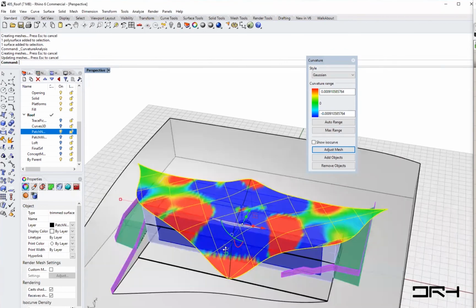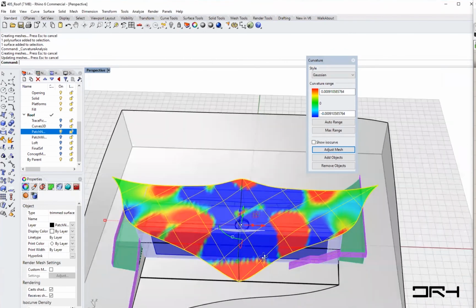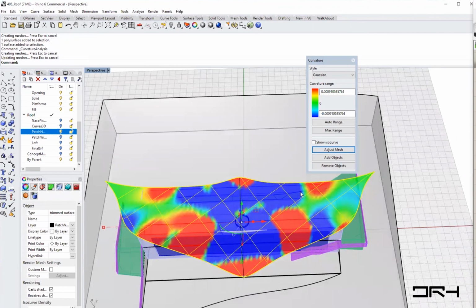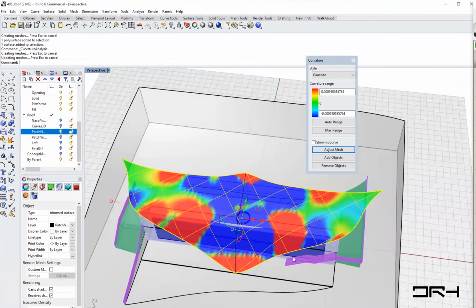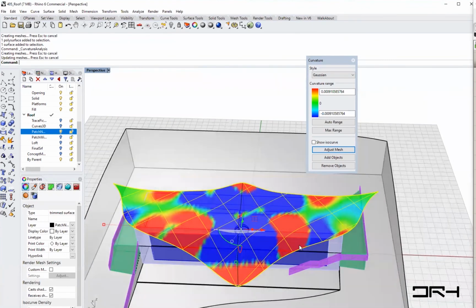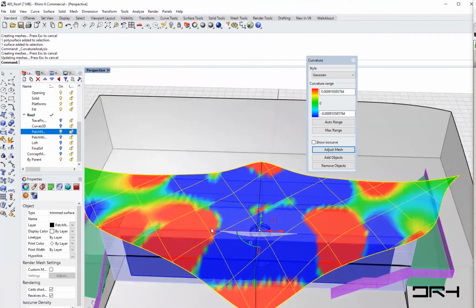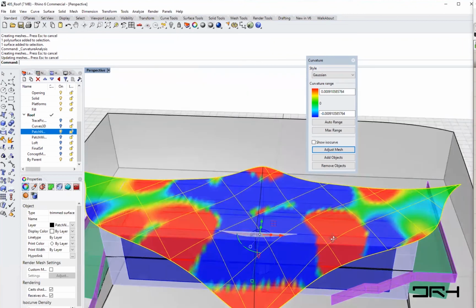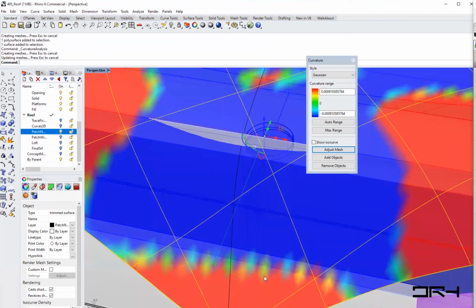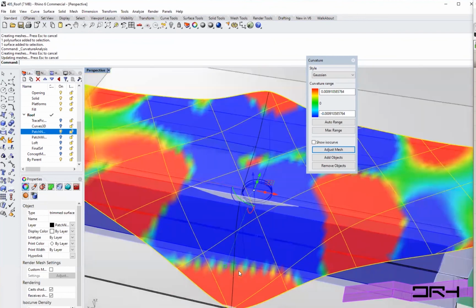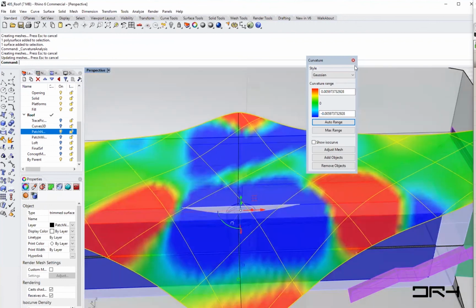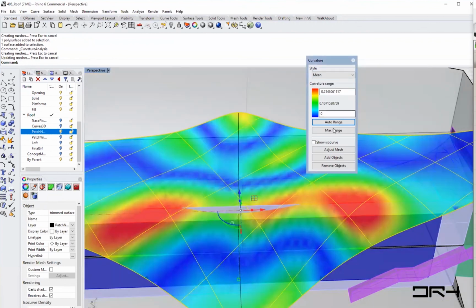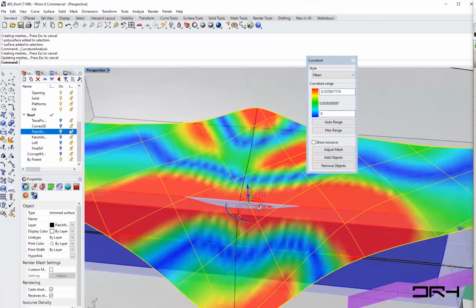So it's easier to see. As you can see here, that's really not symmetrical. Maybe it wasn't very clear when we didn't do the surface analysis, but you can see that the change in curvature here in that surface is definitely not symmetrical. I can see all these little patches of colors here. I'll also auto range, and sometimes the mean curvature gives me a bit more idea.